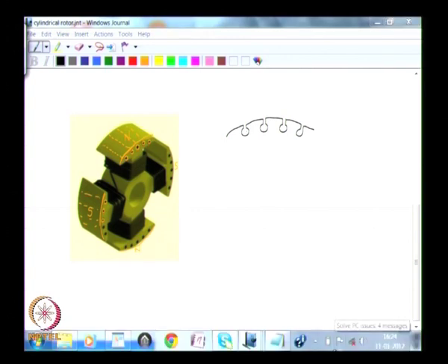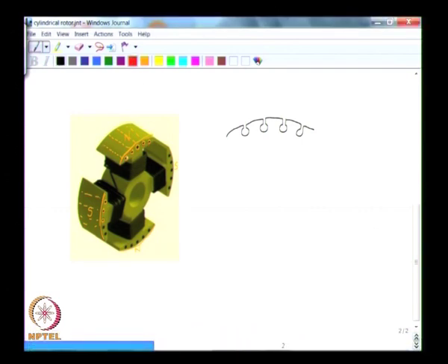is actually used to drive a bar through it. So there is a bar that is driven through this slot and which comes out here, and similarly a bar here which comes out of this, a bar that comes out of this, and so on. So in each pole, through the holes that are provided, you then have bars that are coming out. These bars are known as damper bars.